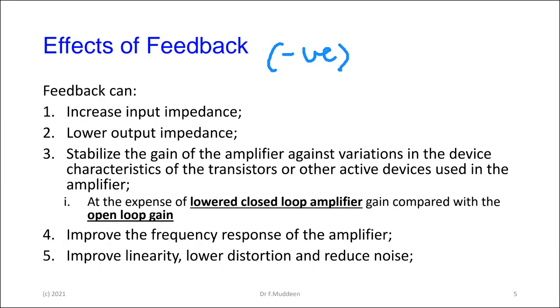So for instance, if you have an amplifier that is measuring the voltages given off by your muscles when they are moving, you're talking about incredibly small voltages. Therefore the input impedance of the circuit has to be very high so that all of that small voltage will appear across the input and not across any source.